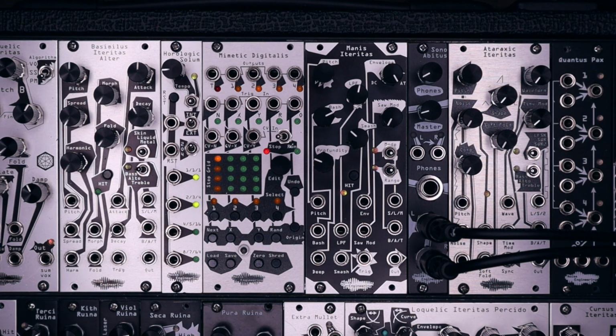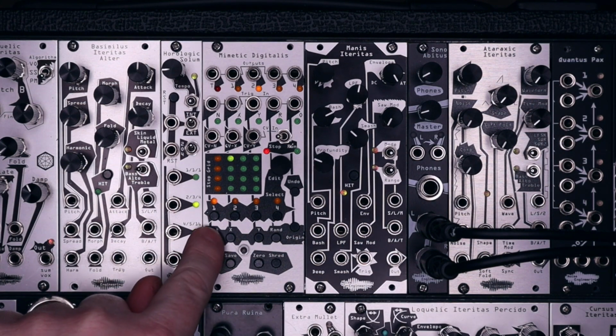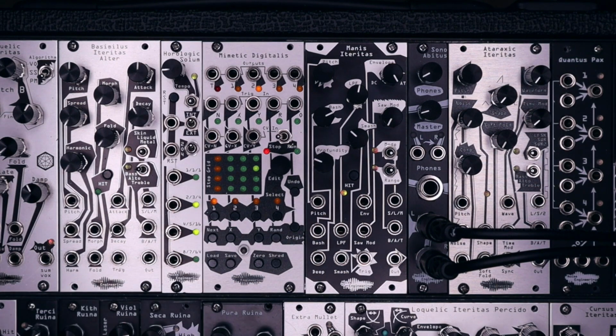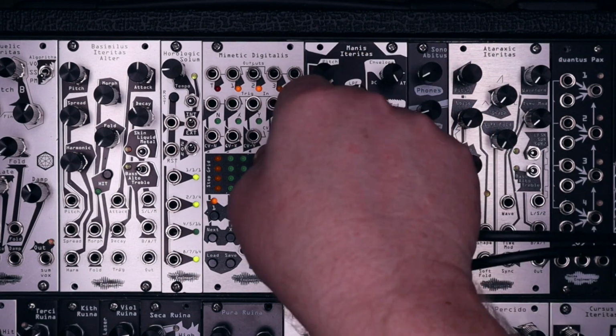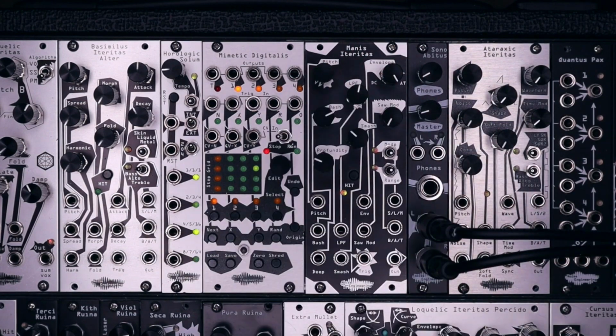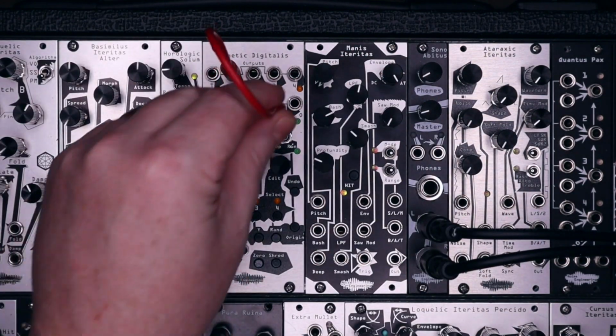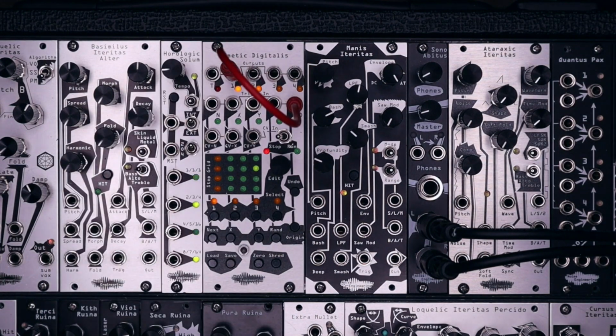First, clear out the MD's step grid by selecting a channel, then holding load and pressing 0. Then advance to 1 step after the number of steps you want to create. Since we're creating a 7/4 pattern, we'll add a high value only on step 8 by pushing and turning clockwise on the encoder. Patch that CV into the O input, which will reset back to the beginning of your pattern.